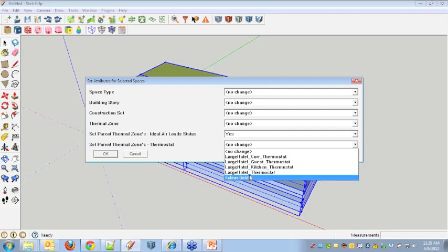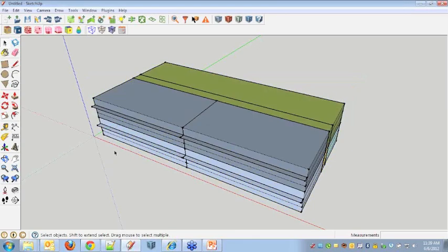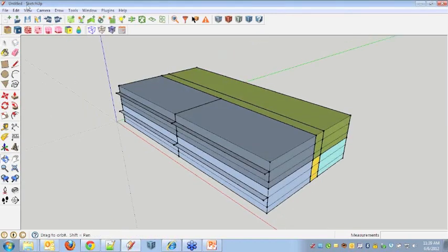And you can pick a thermostat to go with this. So I'm just going to pick the generic large hotel thermostat, but we do have extra thermostats for different space types within the templates. And then you can configure those in the OpenStudio application to match the schedule for your specific project. So if you open 2 hours later, you can just adjust the schedule to represent that. So I'm just going to save this file again. I'm going to give it a new name.